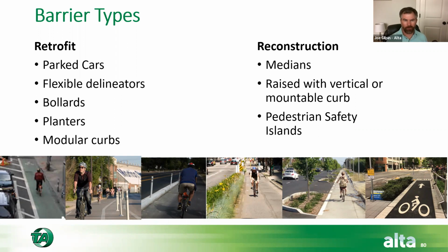And so what we found was that when we did this, we reduced our vehicle-pedestrian and vehicle-bicycle crashes down almost to nothing, but we did have some slightly more fixed object crashes, but very few of those fixed object crashes were substantial. A lot of times they were just minor property damage type crashes. So we made the roadway safer overall, but we did see an increase in fixed object crashes. So take that with a grain of salt or however you will. So it's not a clear answer.